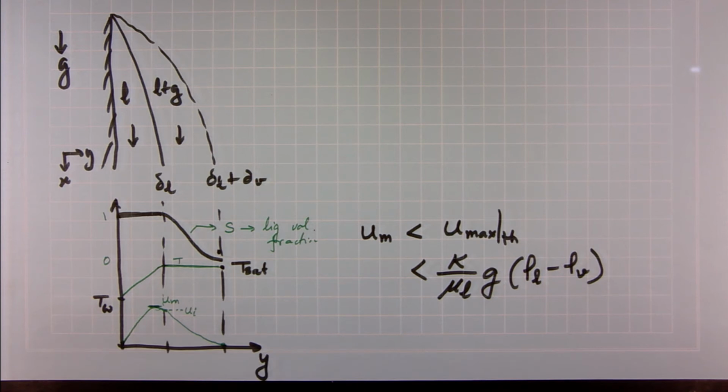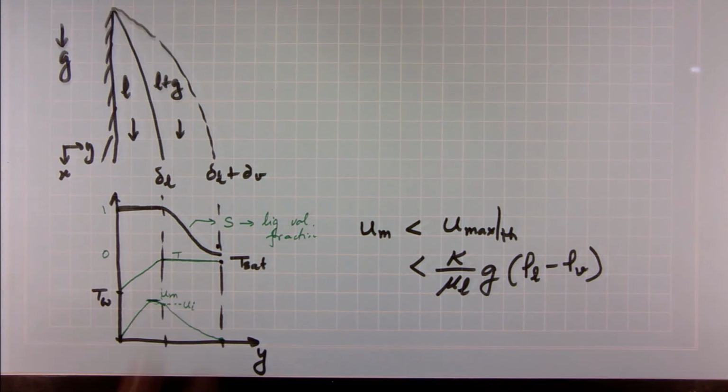If you consider idealized one dimensional flow, this is the maximum velocity that it can attain for a given permeability, for a given gravitational force, and for a given viscosity. It follows directly from Darcy's law. But actual u max will never be equal to that. In practice, it reaches the maximum value slightly before where the liquid film ends, and that value is less than this theoretical maximum.